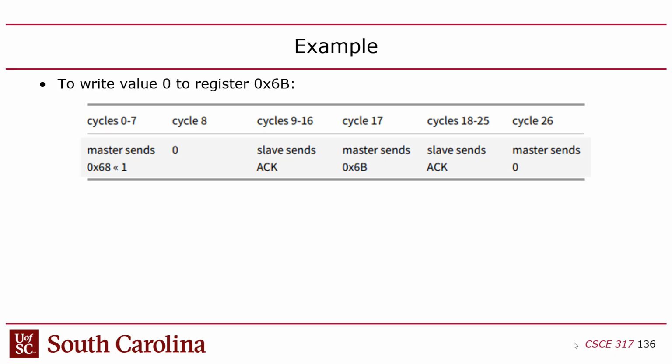The first byte is the device address. The second byte is the register on the device. And the third byte is the data I want to write to that register, right? Okay? Now, what am I writing? What's the purpose of this? What am I doing here? Well, with this sensor, there's a register called the power management register that's used to basically set things up. It turns on the sensor, essentially.